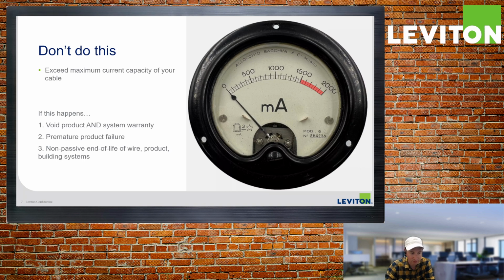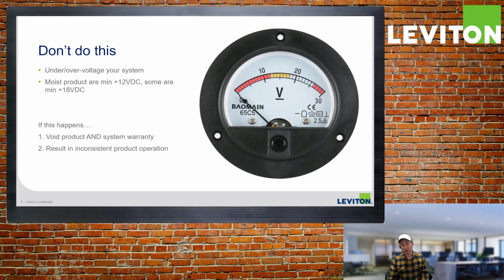Don't do it. Next on the don't do list, do not under or over voltage your system. Our power supplies are all rated for 24 volts. Some of them supply just a little bit more at about 26 volts, and that's okay. Most of our products have a minimum rating of 12 volts. A few of them have a minimum rating of 18 volts. You will see that on the data sheet. So do not provide power supplies in excess of 24 volts nominal on your system, and make sure that every device in your network has suitable voltage in order to operate successfully.